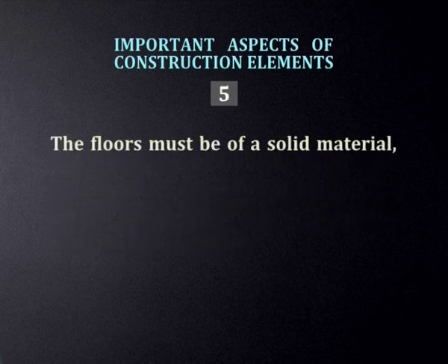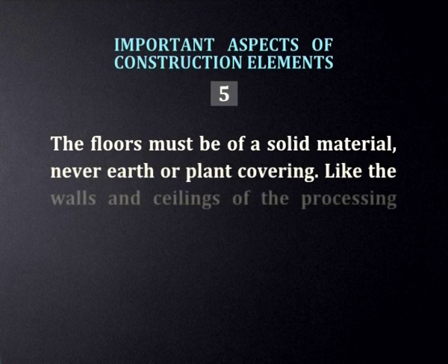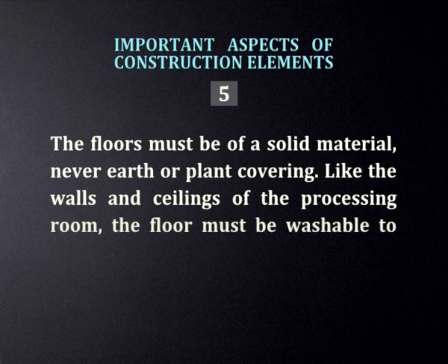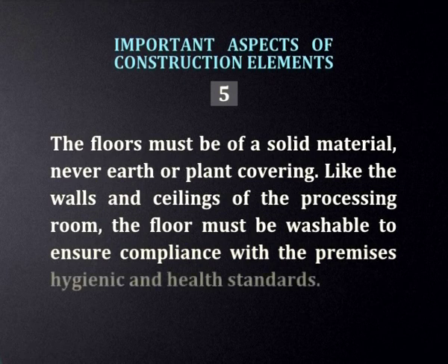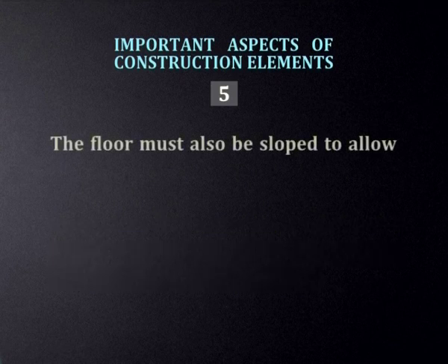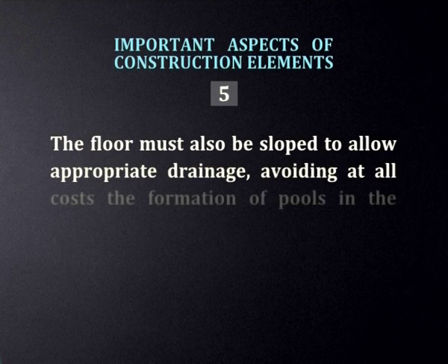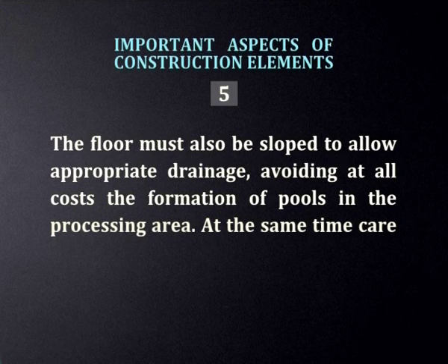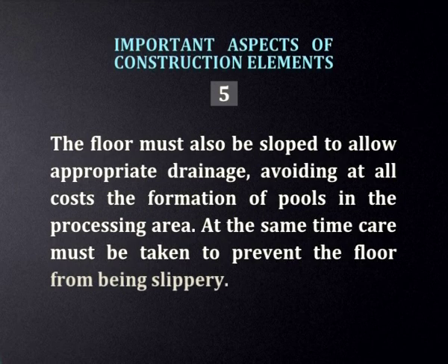The floor must be of a solid material, never earth or plant covering. Like the walls and ceilings of the processing rooms, the floor must be washable to ensure compliance with the premises' hygienic and health standards. The floor must also be sloped to allow appropriate drainage, avoiding at all costs the formation of pools in the processing area. At the same time, care must be taken to prevent the floor from being slippery.